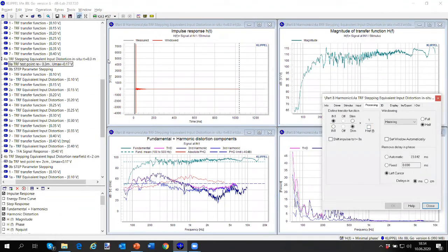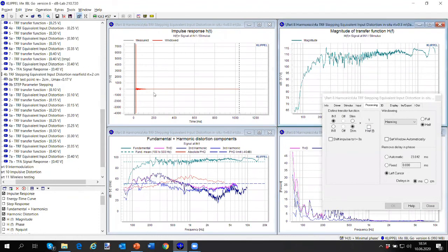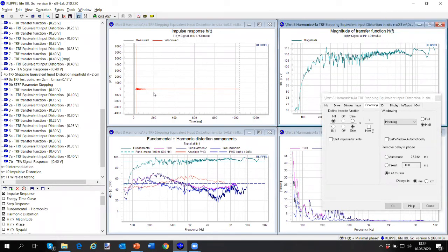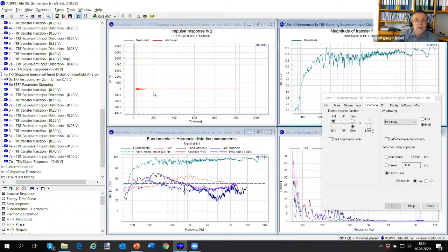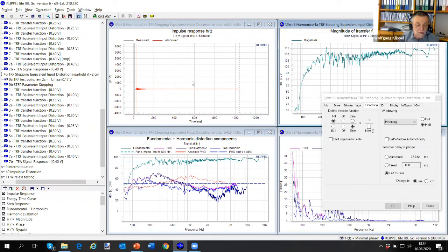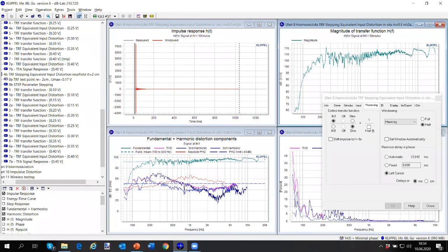Right, very interesting. Is there any benefit from using the KLIPPEL processing while also measuring in an anechoic room? If you have frequency, maybe. I have spoken about this already at the previous sessions. If you have a poor anechoic room, so not so expensive, then you can apply the room correction function at very low frequencies. Right, makes sense. At higher frequencies, we have our windowing and so on. Absolutely. I think we can move along.